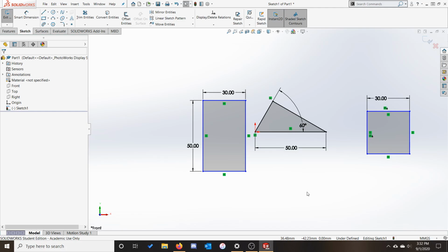If anything is underdefined, left-click drag on the blue components to figure out how they can move, as that often reveals some additional geometric relations that you might have missed in step 2. The exact ordering of dimensions and geometric relations can be a little bit more of an art than a science, but I find that order tends to function fairly well. Of importance, make sure that you use all of the dimensions that you're given the number of times that they're given, in the form that they're given to you in. Do not calculate any dimensions, do not repeat any dimensions, and do not skip any dimensions.